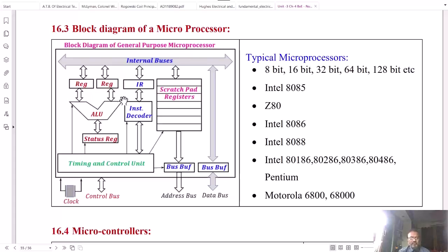For an arithmetic operation to be performed on any data, at least two operands are required. Those are stored in temporary registers, which hold your operands. Here, a register indicates a temporary register implemented using data flip-flops. For example, an 8-bit register is basically a connection of 8 parallel D flip-flops.